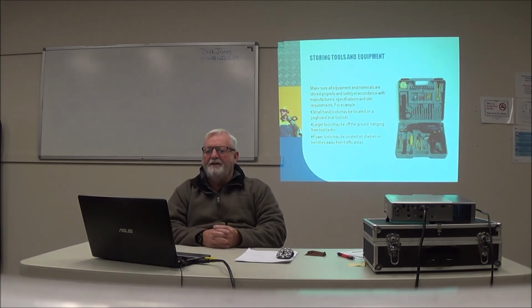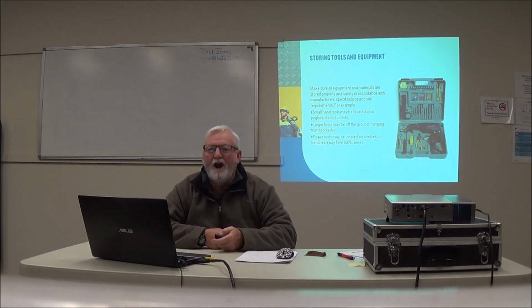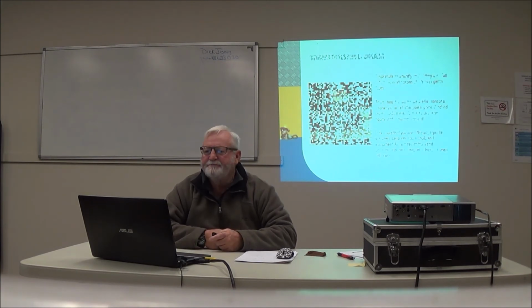Storing tools and equipment. Ensure that all equipment and materials are stored properly and safely in accordance with the manufacturer's specifications and site requirements. For example, small hand tools may be located on a pegboard or in tool kits. Larger tools may be off the ground, hanging from tool racks. Power tools may be located on shelves or benches away from traffic areas.